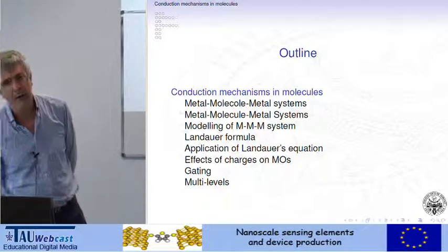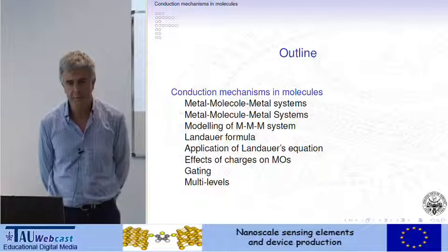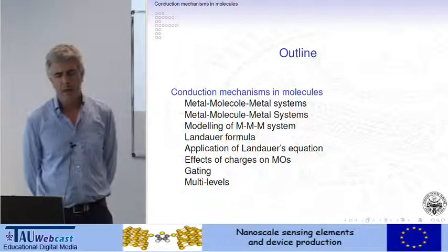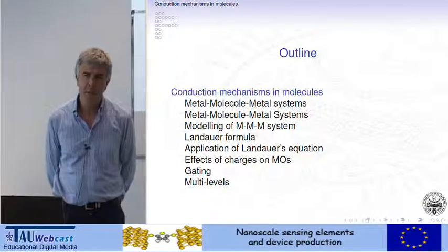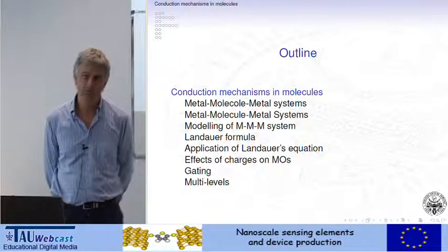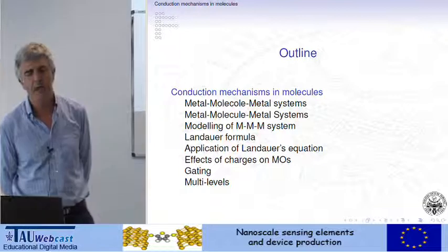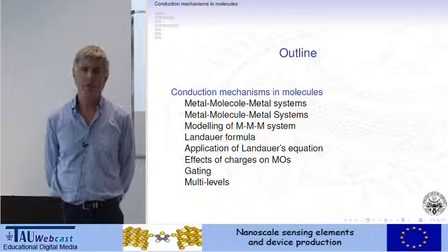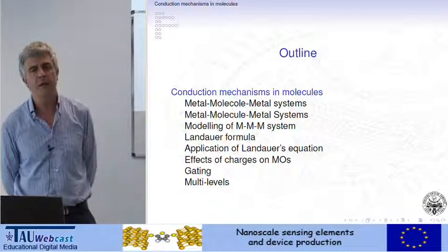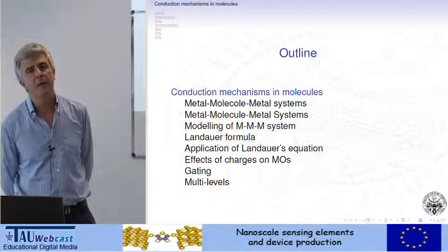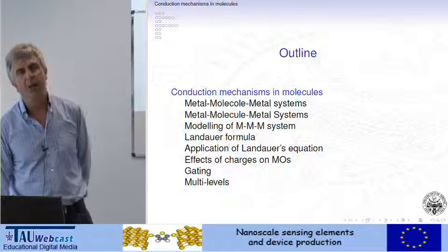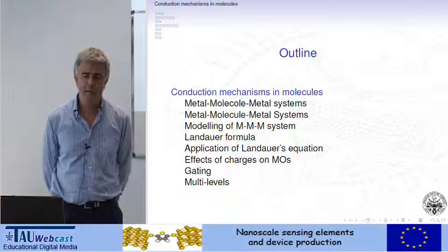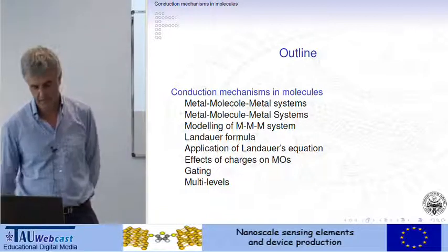After that, we try to apply the Landauer formula to this kind of system. After that, we try to introduce some correction to take into account the effect of charges in molecular orbitals, the gating effect, and at the end, the strategy to apply the Landauer formula when the molecule is described by many molecular levels.